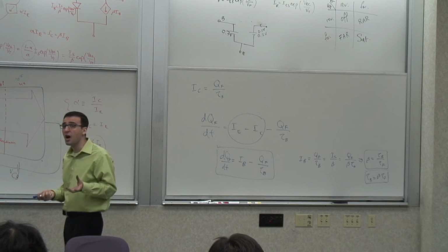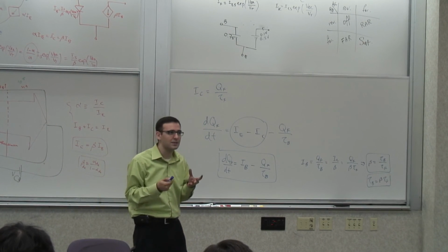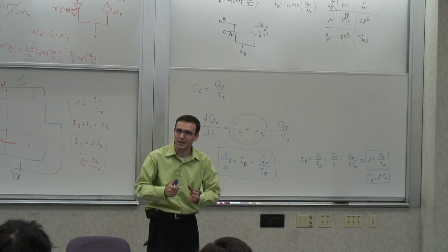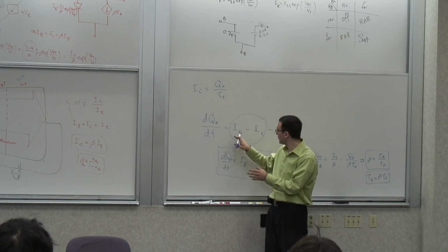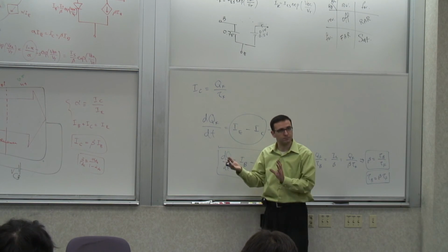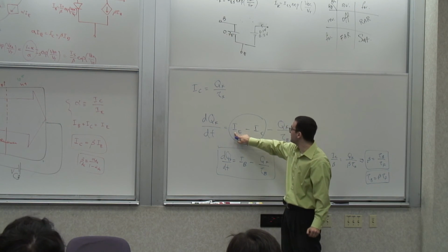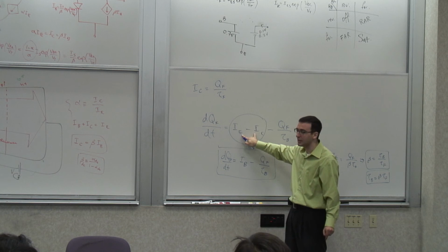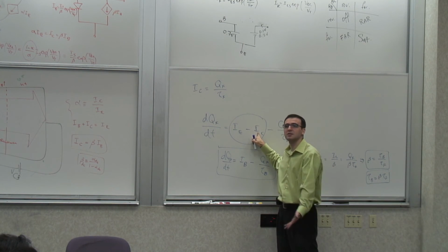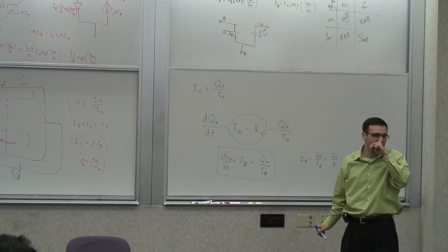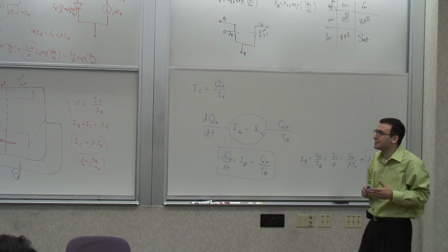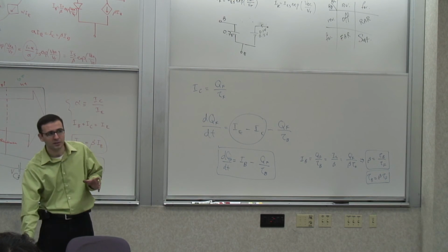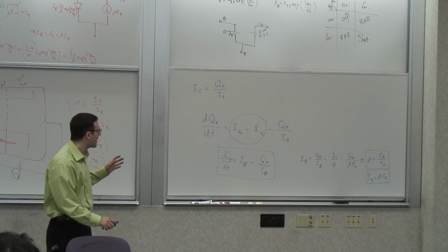So it takes time for the transistor to turn on too. Why? Because you have to build up that base charge. In the beginning, when you apply voltage, it doesn't immediately turn on. It takes a little bit of time for this IB to replenish, for this difference to make the base charge. And therefore IB has to be greater than what would have been in steady state. So you have to basically have a larger current initially, or IC is smaller, in other words. So your collector current is not established immediately. And that determines how fast the transistor can operate. And we'll see that when you calculate the fT of the transistor, which we'll probably do next time, that's determined by tau F. That's one of the parameters.